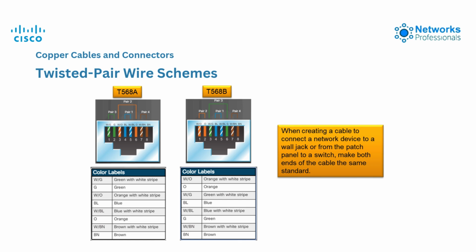T568A standard, less common: pin 1, white green. Pin 2, green. Pin 3, white orange. Pin 4, blue. Pin 5, white blue. Pin 6, orange. Pin 7, white brown. Pin 8, brown. T568B standard, more common: pin 1, white orange.